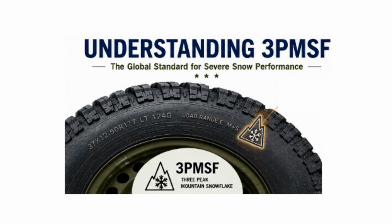The 3PMSF marking stands for Three Peak Mountain Snowflake. It is identified by a snowflake symbol placed inside a mountain with 3 peaks. Unlike the M+S marking, 3PMSF is not based only on tread appearance. It indicates that the tyre has met a defined performance standard for acceleration traction in severe snow conditions. This means a 3PMSF-rated tyre has demonstrated better snow performance than a standard reference tyre during controlled testing.